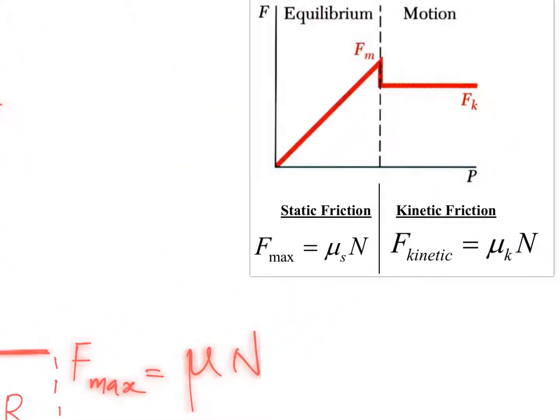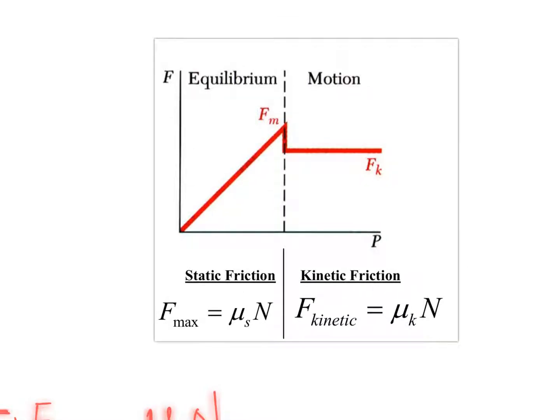And I try to bring your attention to this very important curve where it is clear that as we keep increasing the external force, on this axis we have external force and on this axis we have the friction force. So when you keep increasing the external force, there is a point at which friction force will not further increase. So we are talking about this point because we are interested in computing the minimum force required to move the block up the inclined plane. So that's why we substituted force of friction is equal to mu times the normal force.